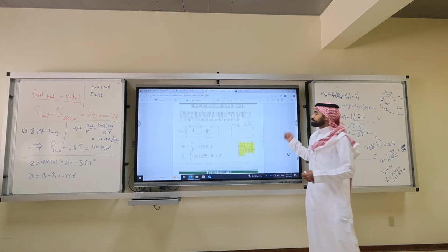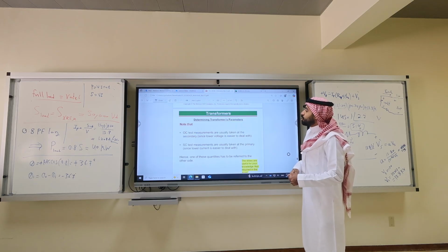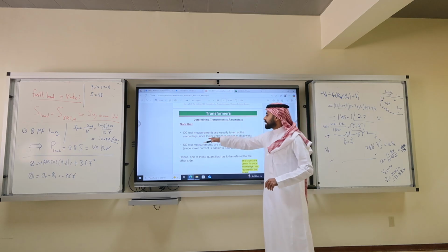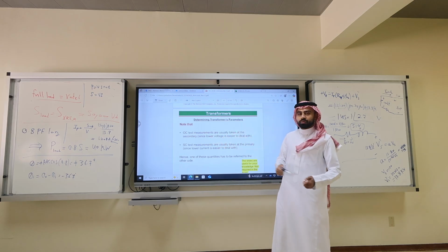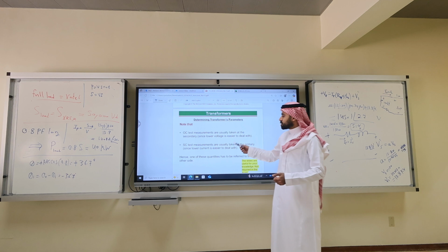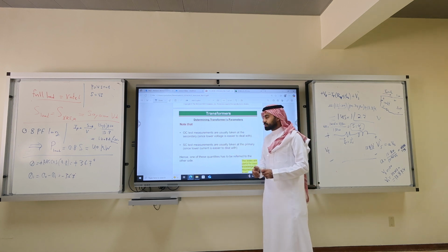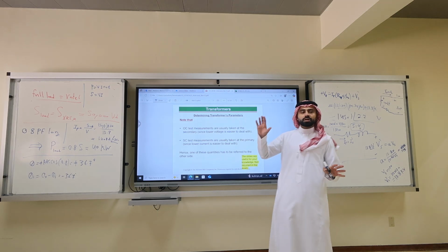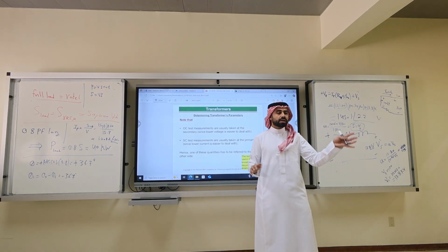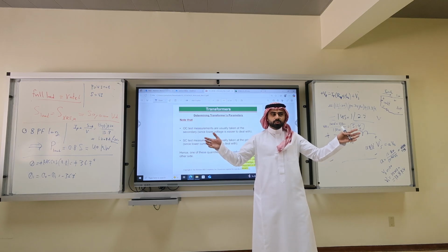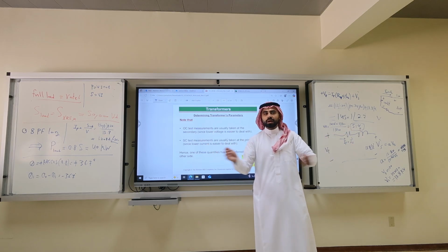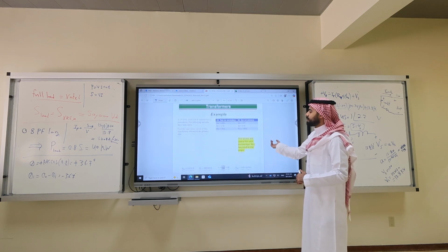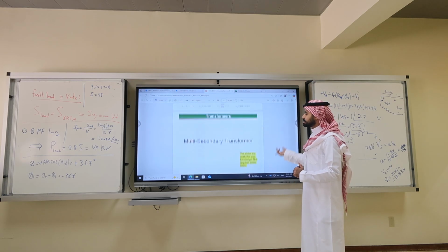Let's continue. Open circuit test measurements are usually, not always, taken at the secondary since lower voltage is easier to deal with. The short circuit test is at the primary side. Hence, one of these quantities has to be referred to the other. So you have components, one referred to primary, usually one referred to secondary. When you write circuit 1 or circuit 2 or circuit 3, you need to refer properly, okay? That's the purpose of this slide. I'm not going to ask you to do the example. This is a numerical example for your own knowledge.